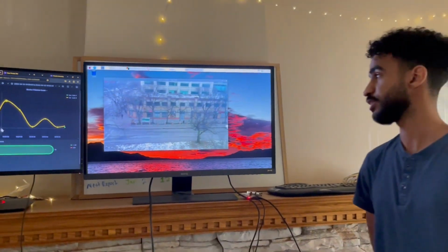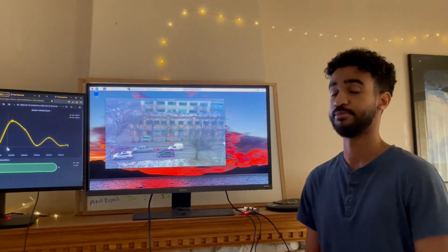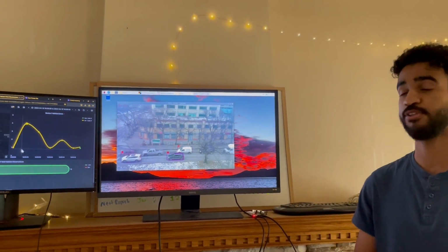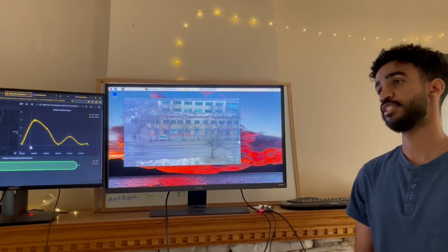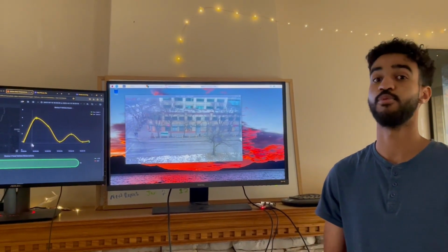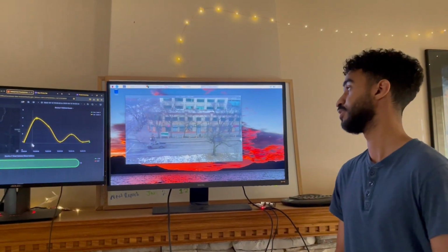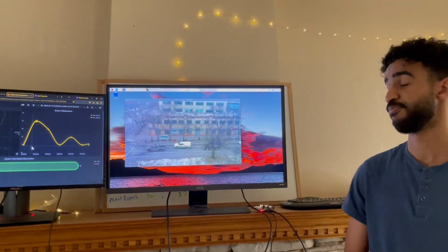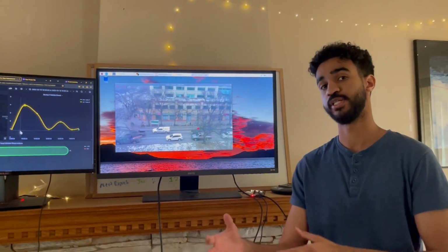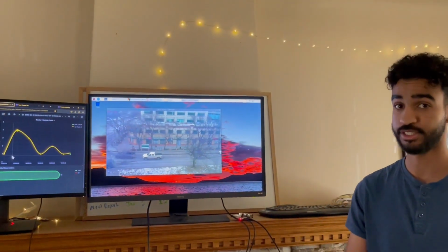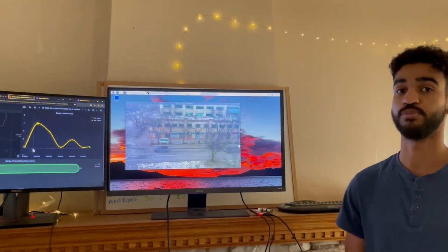Right, so how do we actually accomplish this in real time on a Raspberry Pi? Well, there's actually two things going on here simultaneously. There's an object detection algorithm being run, and then second, there's an object tracking algorithm being run. Now, the object detection algorithm we chose to go with is based on the MobileNet architecture, and MobileNet was developed by Google specifically for edge devices, which makes it extremely efficient. We also then translated the model from TensorFlow into TensorFlow Lite, and then applied post-training quantization, which speeds up the inference time by roughly 75% with minimal hits to performance.